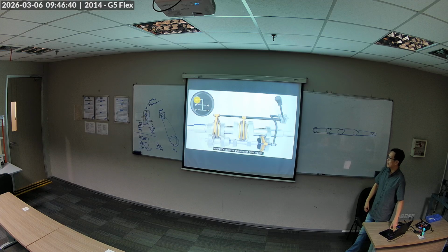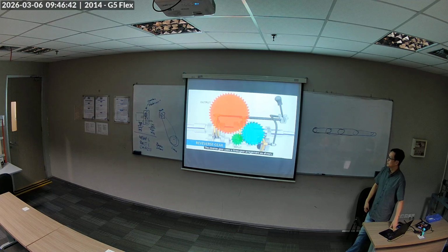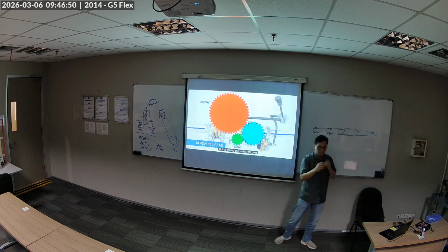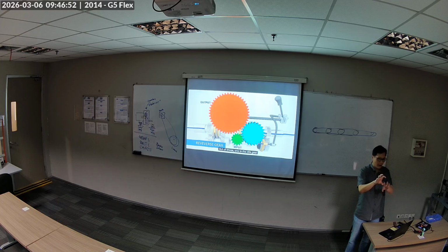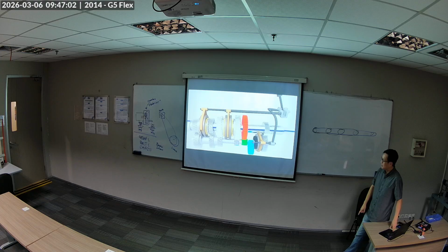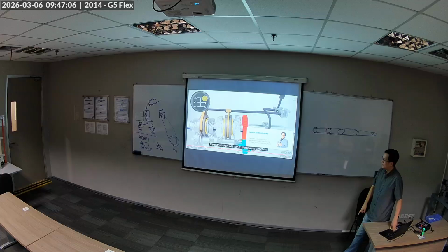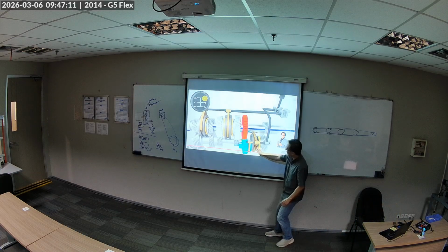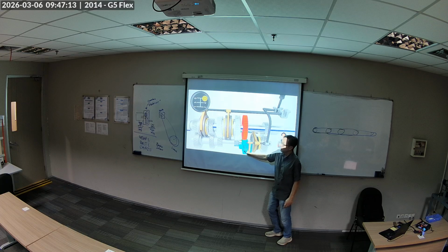Now let's see how the reverse gear works. The reverse gear uses a 3-gear arrangement, as shown. You gotta add an extra gear to reverse, right? Because if you add 1 gear, then it reverses better. Those, one is the idle gear. When the idle gear is pushed and connected to the other 2 gears, the output shaft will turn in the reverse direction. Okay, so the 5th gear and R.